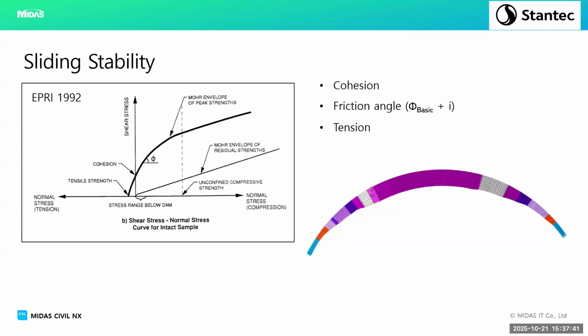And the interface between the dam, the concrete, and the rock is often, or very often, stronger than the actual localized joint you might have just below it. I've actually seen that through coring. We've cored through this dam, from the downstream right to about the middle of the interface, and we've got some decent cores. So what's important to quantify when we're looking at this, particularly for concrete on rock,